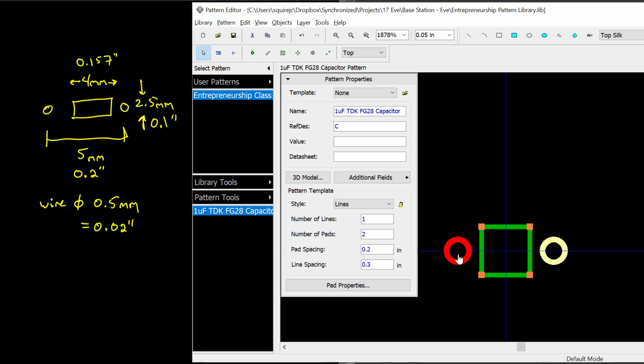But with the way the pads are placed outside the body of the component, we couldn't place another component in the middle of this if we wanted to. So shortening the length of the silk screen of the body of this component is perfectly fine since there's no danger of putting another component in lengthwise, since it would interfere with the pads.